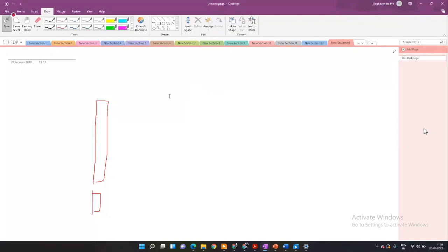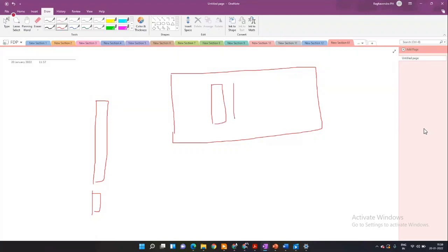So what we do is we also have data acquisition chassis. You also have RF chassis where you have PCIe, something called MXI cards over here, which you can think of as similar to the data acquisition cards that I mentioned. These cards will be placed inside a chassis, and they will have your PCIe ports. Now, there are chassis where you can put 4 USRPs at a time. Since they're Rios, they have 2 RF channels each, so you'll be able to achieve an 8x8 MIMO system.